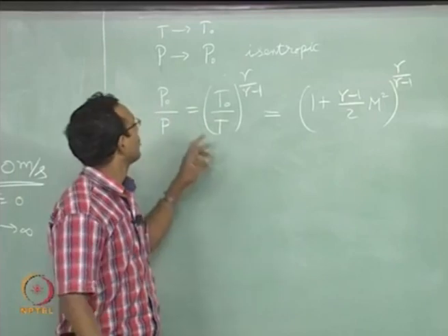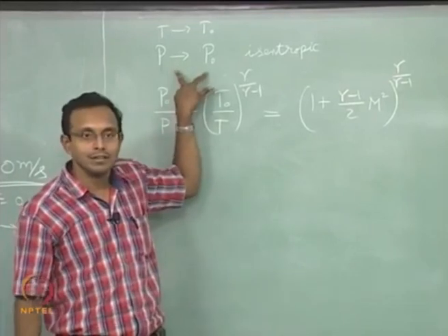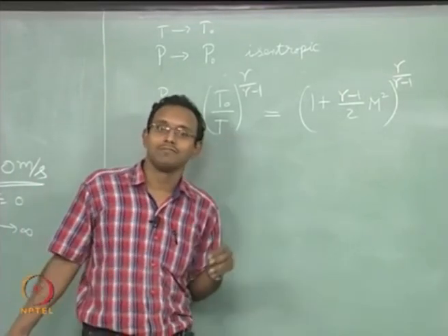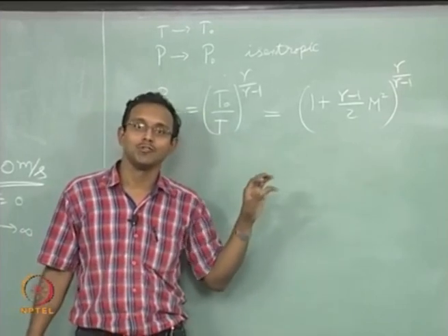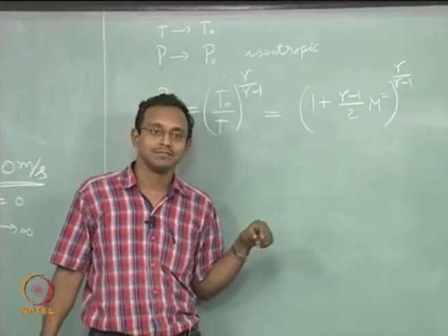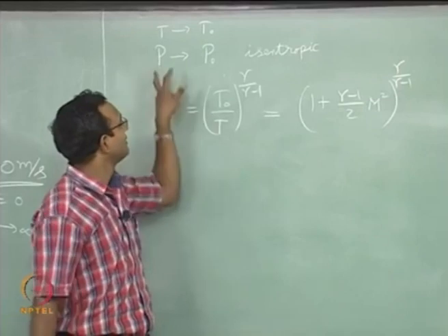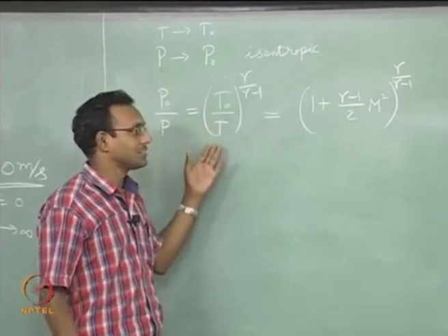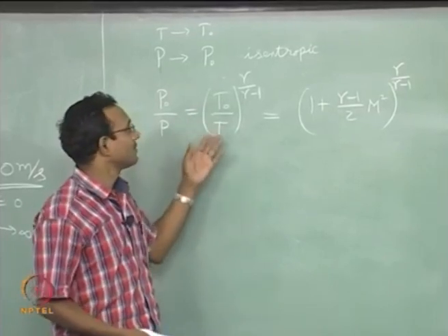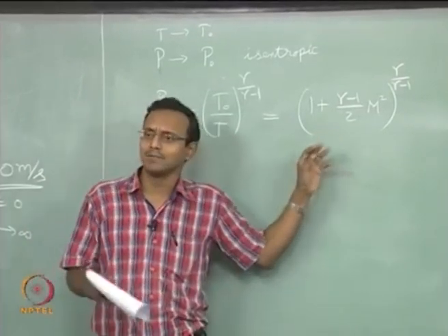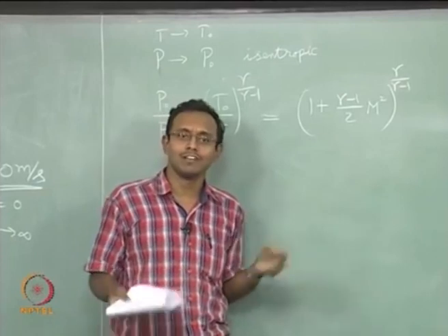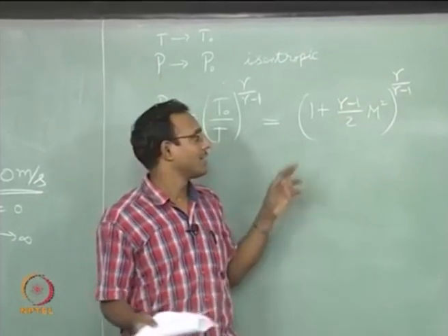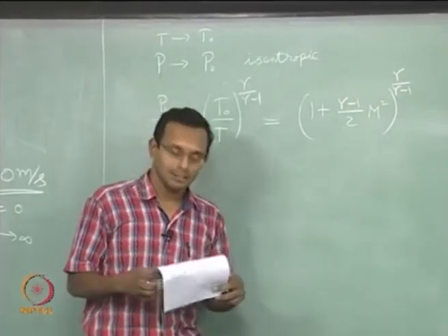It needs to be isentropic only for pressure. Temperature, it is enough that energy equation saying there is no more q dot in, okay. If that is the case, then that expression is valid. You just derived it from energy equation just today, right? When we derived it that way, we found that it was directly equal to this directly from energy equation. That was only for adiabatic steady flow, and I got to this point, okay.